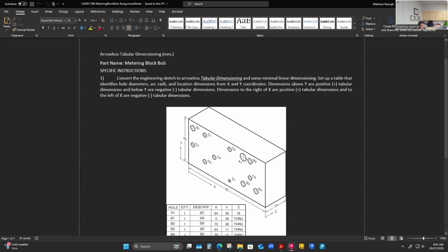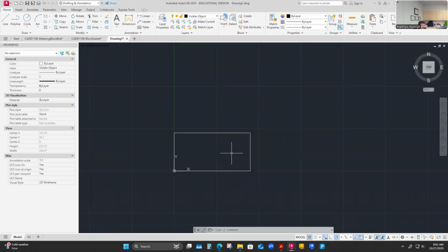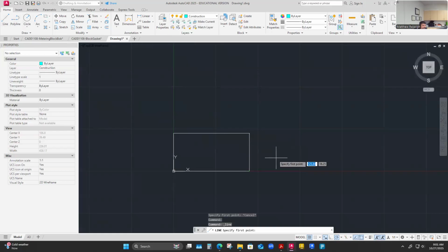And then 24 deep. So I might project over to a right side view. So that's my front view. On this particular one, we only need a right side view, and we need a simplified one at that. This is where I would do maybe some construction to keep it in orthographic alignment, but I'm going to come over here so far. I don't know, how far do I need? Maybe only 75 millimeters over is all I need. And then this is going to be the same height.